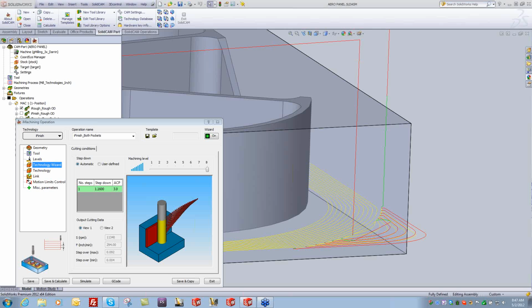The thing about iMachining is it shines in 3 places. It's made for bulk material removal, exotic materials, or really small tools. Because we're managing the tool's engagement, small tools aren't a problem because we're not going to break them. Because we're managing the tool's engagement, we can take a lot of material out very quickly. And of course, exotic materials are always tough on both. So again, the engagement angle of the tool is what really speeds everything up. However, you can use this in 3-axis positioning, or 5-axis positioning using 3-axis iMachining.